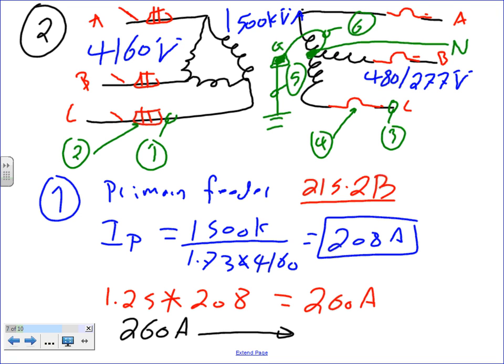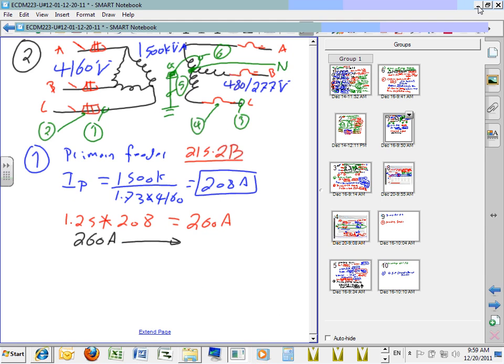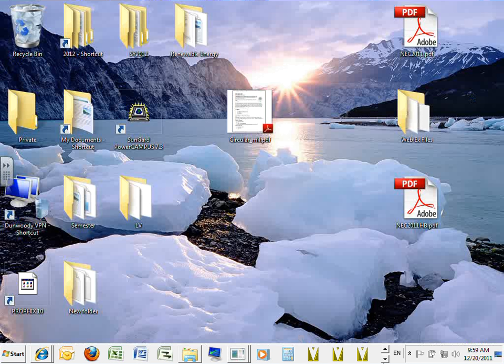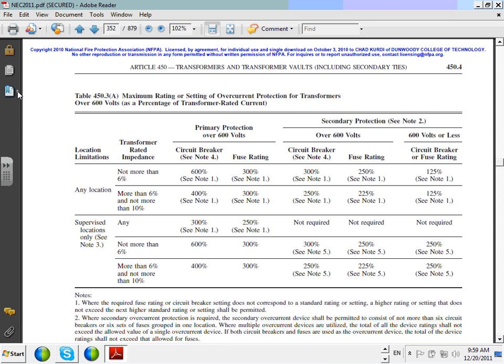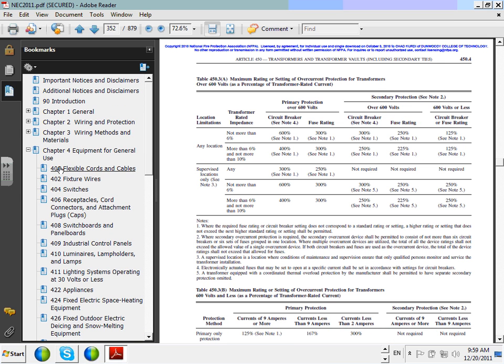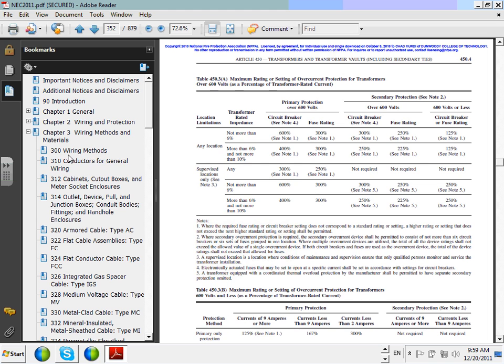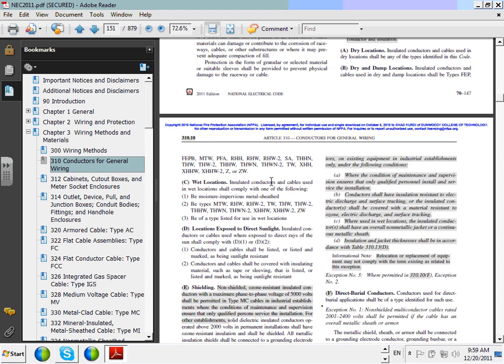That's where I want you to go quick into table 310.19. They changed the numbers. Let's go to this table. To size it, I'm going to run into the NEC code book for help here and find a medium voltage cable that can carry this baby. To help me with this, I'm going back to Article 310.